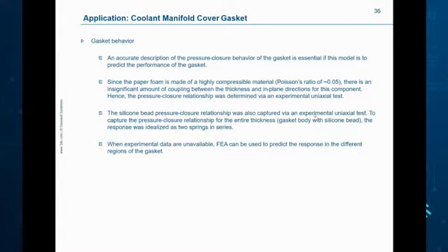An accurate description of the pressure closure behavior of the gasket is essential if this model is to predict the performance of the gasket. Since the paper foam is made of a highly compressible material, there is an insignificant amount of coupling between the thickness and in-plane directions for this component.